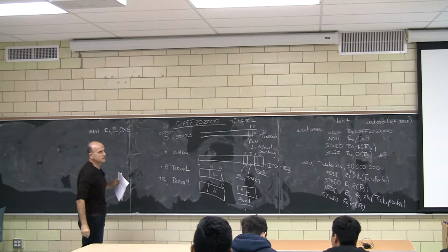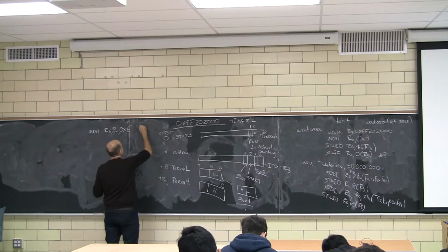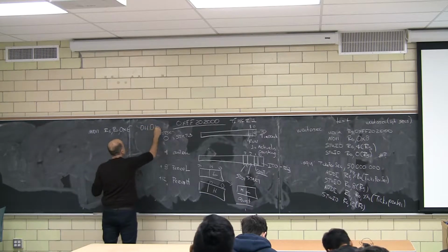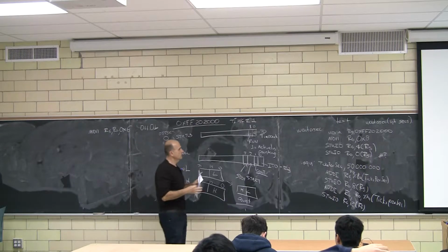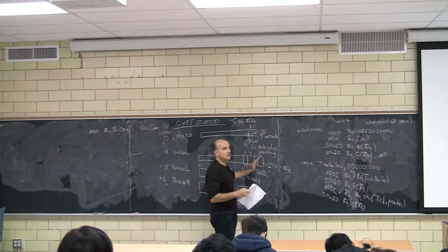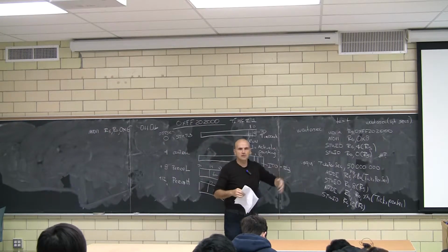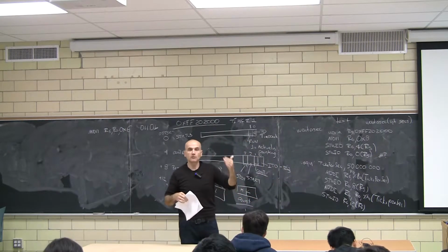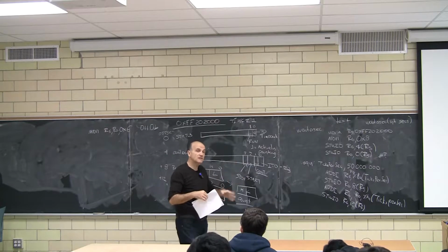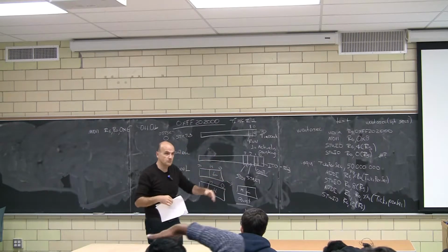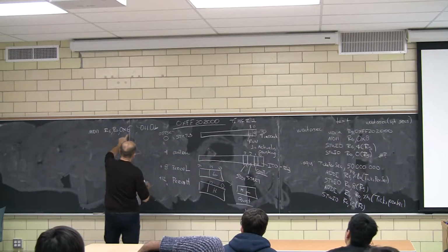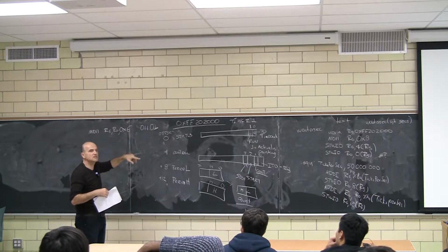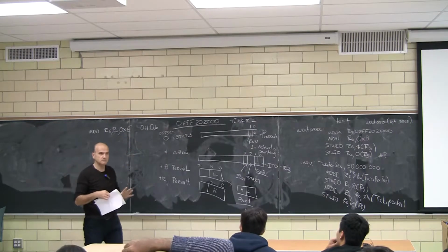Now 6 is the following in binary. So we're going to be setting start and continuous mode because we want to be counting a lot of seconds. Okay. So we're going to have it start counting 1 second, and then we tell it once you finish counting, please count the next one. We're going to have a longer discussion why this is better to be 6 rather than just 4, which is just count 1.